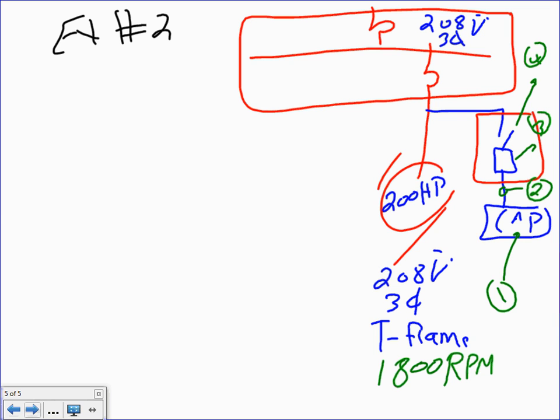And if anybody is wondering what I'm doing here, in reality, how do they tie these wires together? They have 2 lugs. One lug right here, you have 2 lugs, one going here and one going here. Because you can't just go cut the wire and tie to it. The circuit breaker has 2 lugs, and one will go directly into the motor. The other one will go to the disconnect switch. That's one way. Or you can have a J-box here. But you can't just put a cable and tie to it physically. You can have a J-box right here, or a pull box, and tap from the conductor.